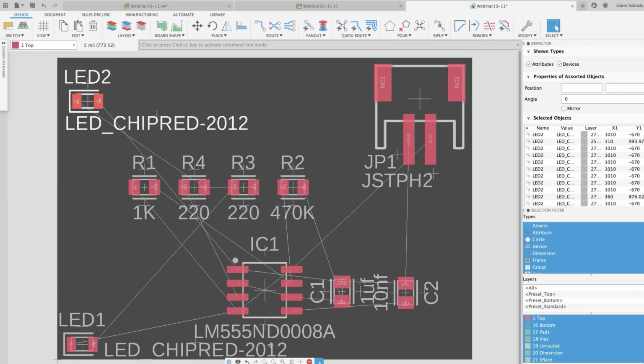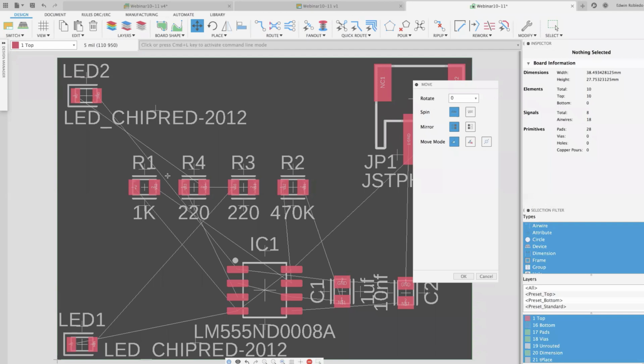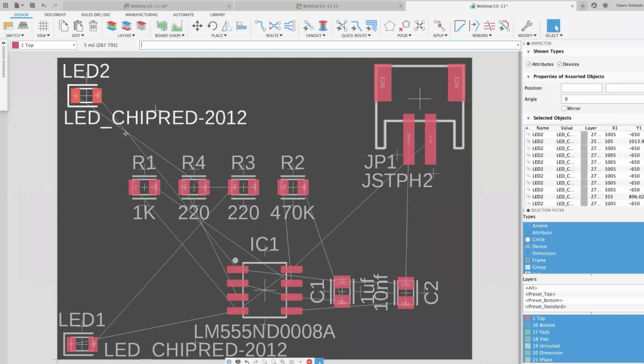Now I'm going to start using the route command, but before that, I want to optimize my connections. Remember I was using the term rat's nest? Well, that's what we're going to be using. It's called rat's nest. That's the name of the command to optimize my connections. If you're doing the same design together with me, it's possible that these results might be slightly different, might have a slightly different path, but that doesn't mean it's wrong.